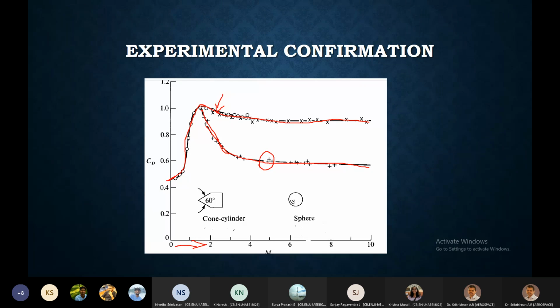Please remember, we are talking in terms of the non-dimensional parameters. So, for example, if I am talking about pressure, what I am saying here being independent is not pressure. I am not saying that pressure is not a function of Mach number. This is not what I am saying. What I am saying is that the non-dimensional pressure, that is P by rho v infinity squared, is independent of Mach number.